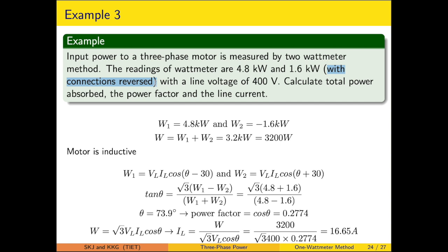Now when we will be measuring a power in case of wattmeter, when it is reading negative, that negative deflection cannot be read, and to facilitate that negative reading we will be changing the pressure coil connection, and that particular is done with the help of DPDT, and you will be having the experience to do it in the laboratory likewise.